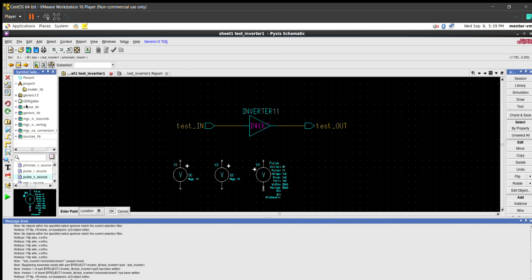And then we're going to need to go back to the generic library, and we're going to get the VDD. And we're also going to get VSS. So we didn't define the port of ground to be VSS in the inverter, but often there are global nets such as VSS, and if you're using a process where you have split power supply, so maybe plus or minus 2.5 volts or something, the VSS would be the lower voltage, whereas ground is actually 0. So you probably don't need to do this step for this inverter, but I'm just going to show it to you now in this schematic.